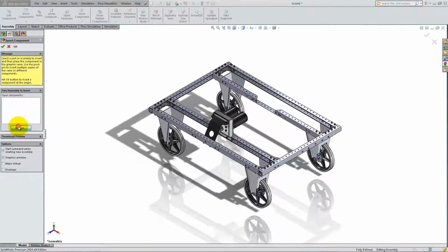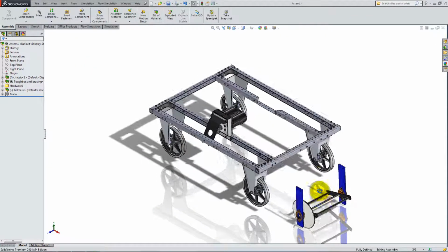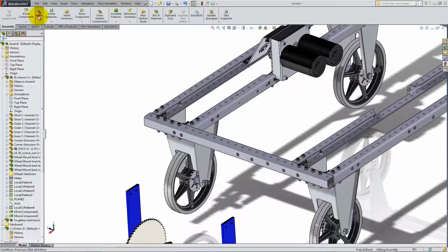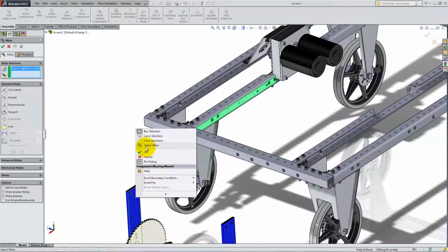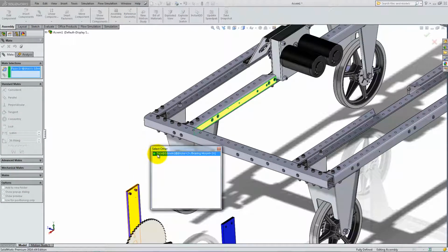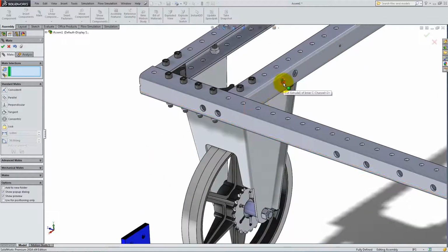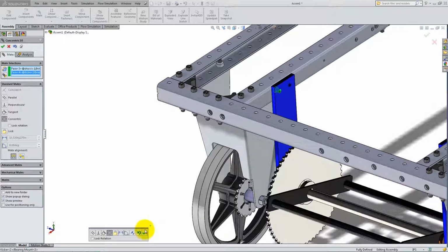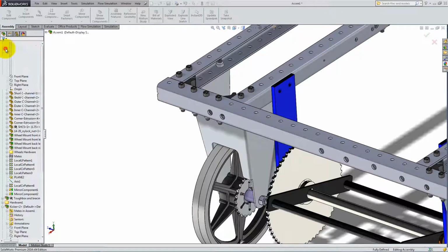Next, switch to isometric view and insert the kicker assembly. Add a coincident mate to place it next to the inner C-frame. Instead of rotating the model, right-click and select Other in order to choose the appropriate face of the bearing mount. Add a concentric relation between the first hole on the frame and the bearing mount, and the parallel mate to fix the mounts vertically.